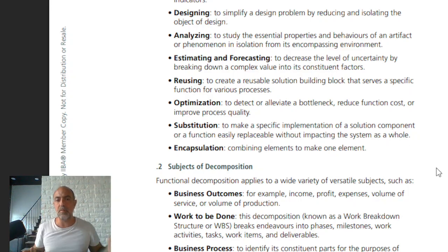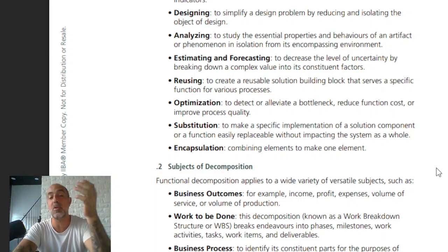when it comes to building construction, what they do is they measure based on meter square of construction, because every meter square of a wall requires water, cement, blocks, some work, whether they're building on top of each other, and whether they're plastering or painting. Every meter square costs X amount, and that's how they estimate buildings. So you get it? They didn't go all the way deep into everything, but they did at one point, and based on that, they don't have to go that deep again.